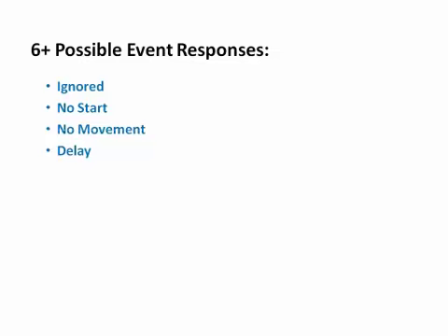This is a case where the systems necessary to move an item away from an activity are down. The no movement case does not prevent processing of the item, but prevents that item from leaving. And if there are limitations on your activities that say you cannot process a second item while the first item is there, then the process will be forced to shut down until the first item can move on. We also have the stop and resume. This is the case where we get interrupted, but once the interruption is terminated, we can resume processing from the point where we left off and no additional time is lost.